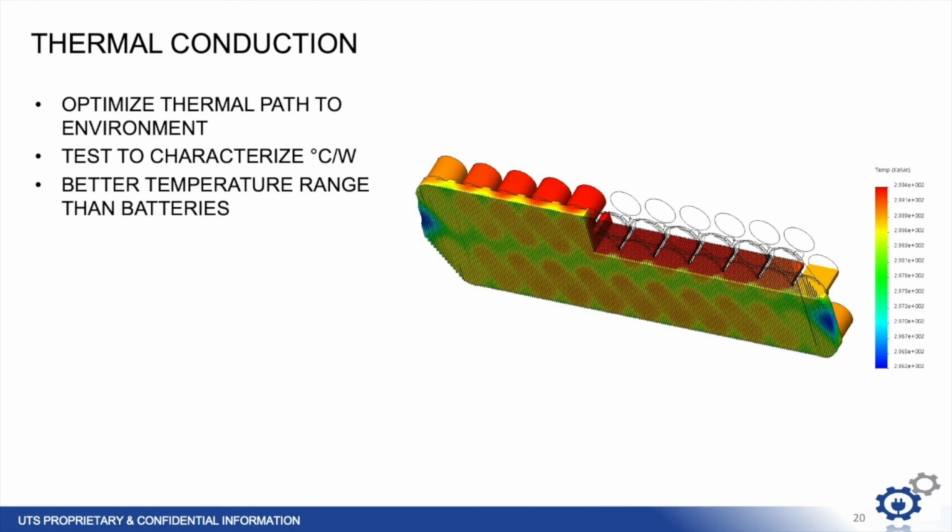Next, we look at the thermal path. It is helpful to revisit the cell structure again. Here we find that the cell as a whole is fairly well uniform, being mainly constructed from aluminum and filled with a liquid that avoids large air gaps. However, the paths of best electrical flow tend to be the paths of best thermal flow. So it may be helpful to consider the terminals, and therefore the bus bars, as not only a feature for electrical conduction, but also thermal conduction.